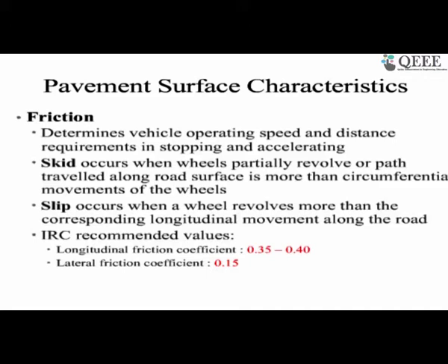The reason behind this is that we need the vehicle to be laterally stable, because if the vehicle is sliding in the lateral direction, it is very difficult to control, and we need absolute safety in that direction. In that case, the vehicle can be thrown off the road and get into an accident. Whereas in the longitudinal direction, there is a little better control because of the steering and other things, and that's where we can get this friction.